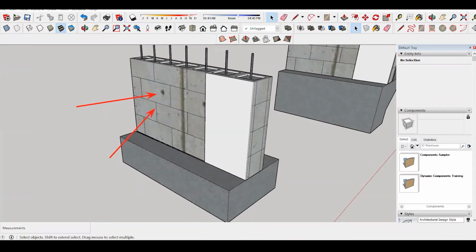So what do we do? We introduce a layer of plaster wall, which is right here, and this helps to cover all the lines and the imperfections as the wall was being laid. So this layer of plaster wall removes all these lines and gives the wall a smooth surface so that we can apply paint after. So that's what that is for.